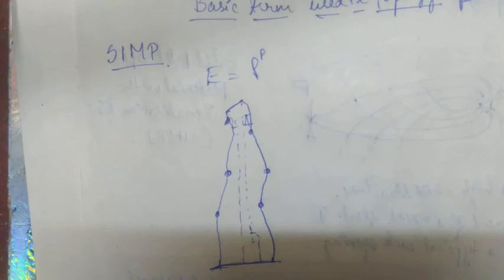Lateral loading was applied to the tower, and topological optimization studies were performed on the entire exterior surface as well as the perimeter surface. Despite the highly irregular shape of the tower, it was found that a series of discrete structural load paths could be identified in the form resulting from the topological optimization.